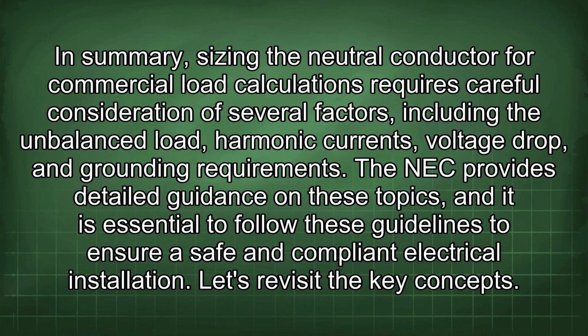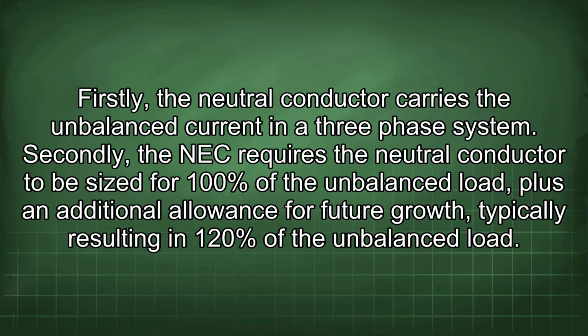Let's revisit the key concepts. Firstly, the neutral conductor carries the unbalanced current in a three-phase system. Secondly, the NEC requires the neutral conductor to be sized for 100% of the unbalanced load, plus an additional allowance for future growth, typically resulting in 120% of the unbalanced load.